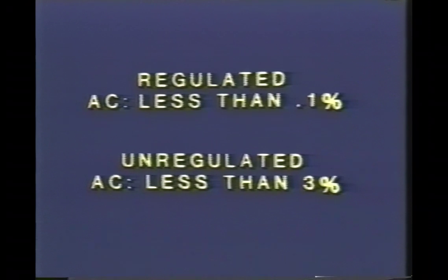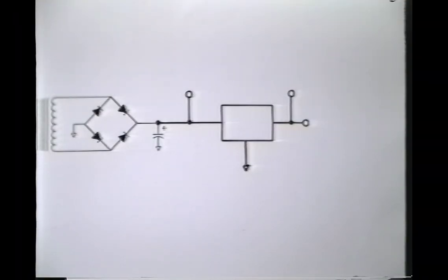However, if you start to get up around 5% ripple, chances are pretty good your capacitor is starting to fail, so keep an eye on it. I try to use about 3% as the figure, and if it goes over 3%, I usually change the filter capacitor. If the output voltage of the regulator does read too low on DC, but there's no AC when you